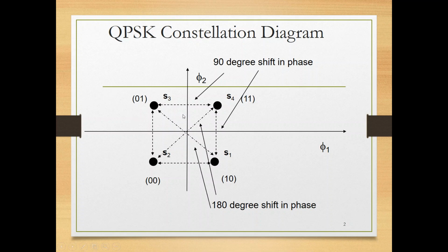And we remember that we drew the constellation diagram of QPSK. This is the diagram you are seeing here, and we call it the constellation diagram. It is a visualization of where you place your symbols in the I and Q diagram. This is not something you can see in real practical life, but you use it to visualize the effect of your modulation on the amplitude and phase of your carrier. So basically, this is for understanding and visualization. You can see this diagram, for example, in a spectrum analyzer. This is a device you can buy to analyze the signals on the air, where you can have a window that shows you the constellation diagram of your received signal.